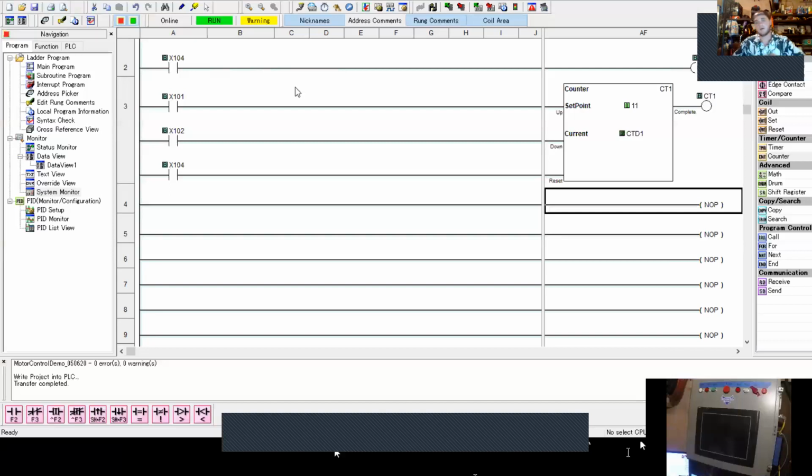Okay. Now, if you're not sure where that is in our data registers, you can go to setup and system configuration. And unfortunately, you're not going to be able to see this on my screen, but if you do this on your software, you'll be able to see it. If you go to IO4, you'll see that the output is DF5, 6, 7, and 8. And so we can sort of deduce that DF5 is associated with channel 1 on this analog output card.